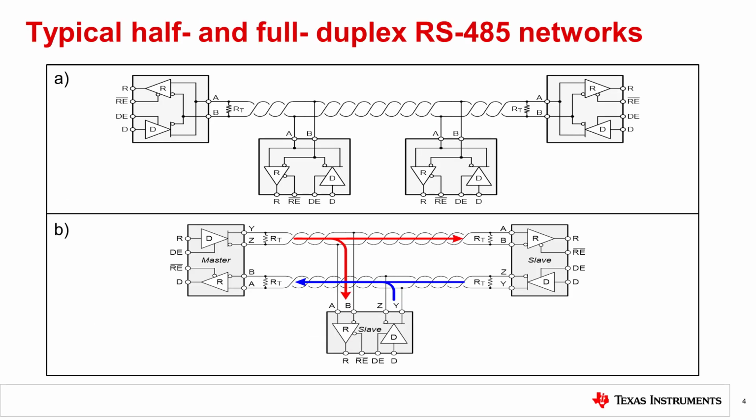An RS-485 bus consists of multiple transceivers connecting in parallel to a bus cable. To eliminate line reflections, each cable end is terminated with a termination resistor, denoted as RT, whose value matches the characteristic impedance, denoted as Z0, of the cable. This method, known as parallel termination, allows for higher data rates for longer cable length.